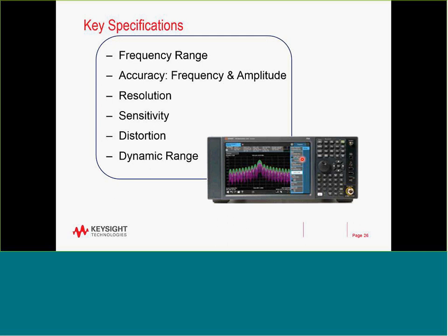How can you see a signal that is very, very small? The analyzer itself has some distortion. It will create some distortion below the distortion that you want to measure. Otherwise, it will show up in the spectrum analyzer. I'll show you a way of discriminating whether these distortions are mine, or they belong to the analyzer, later on.